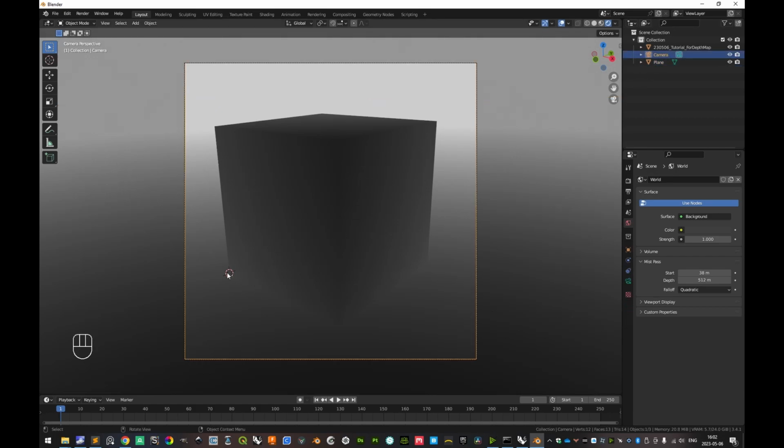All right, so now we have the, what is it called now, the 3D cursor. We have it here in the XYZ origin. We can hold shift and right click to readjust it, and by pressing the period key we can choose where we pivot, and we pivot from the 3D cursor or around the 3D cursor.